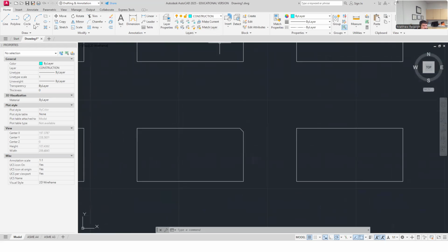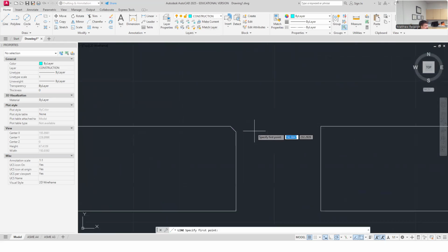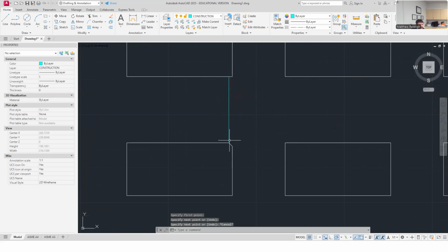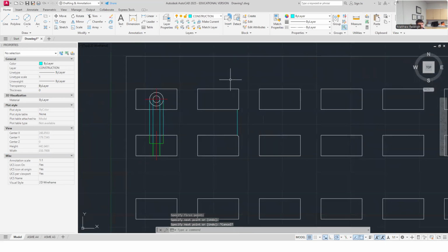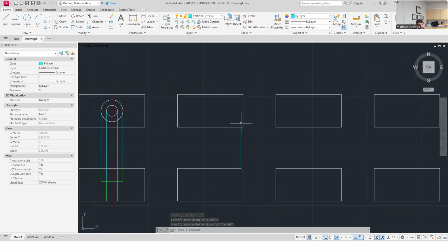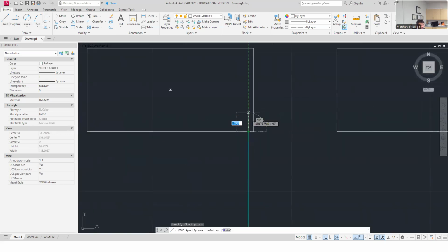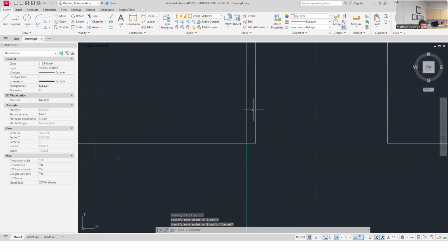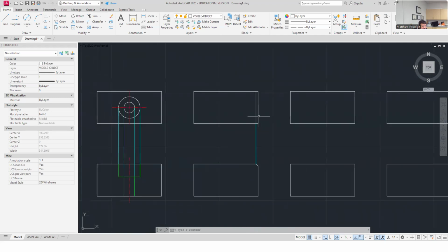And then I'm going to just project these up. So how it should show up in the top view is I should see this as a visible line in the top view, because that's kind of like material that's been notched away and is falling down and away. When I look at the top view, that little chamfer is falling down and away. So it looks like this, right? It's just a line. It's really simple to draw, yes, but the concept is this is falling down and away from me, from this point down to there. That's falling away from me.